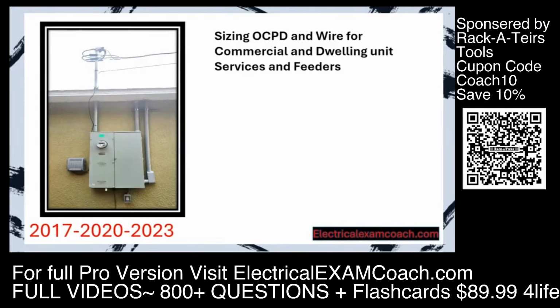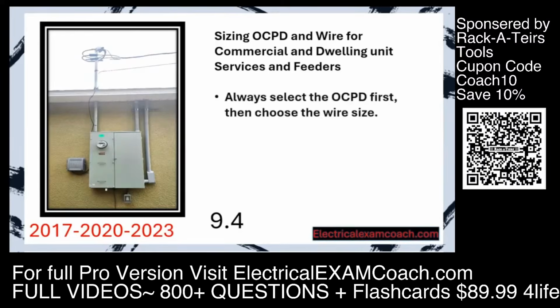I am the electrical code coach from electricalexamcoach.com, and this is lesson 9.4 in our video series. In this lesson, we're going to be sizing the overcurrent protective devices and wire for commercial and dwelling unit services and feeders. We're actually going to start with commercial because it's easier, believe it or not. Always remember that we're going to select our overcurrent protective device first, and then choose our wire size. Also, the overcurrent protective device size is the size of the service.